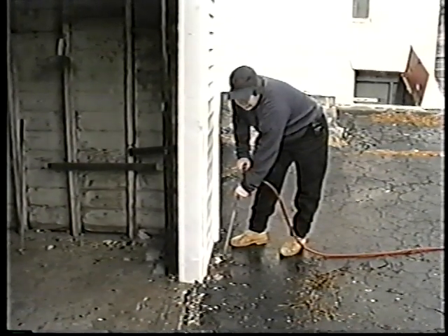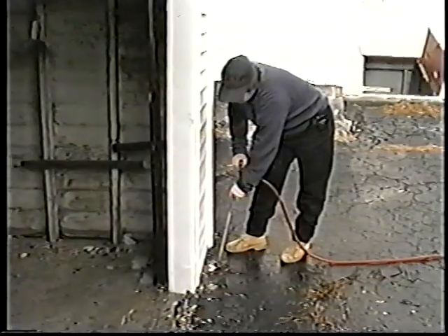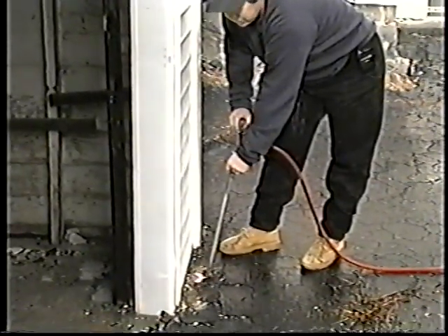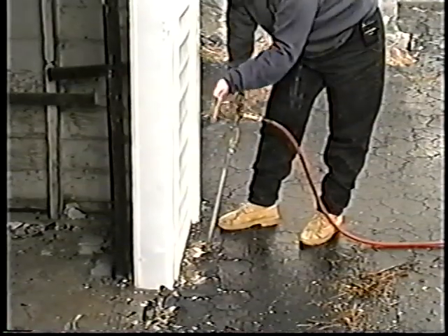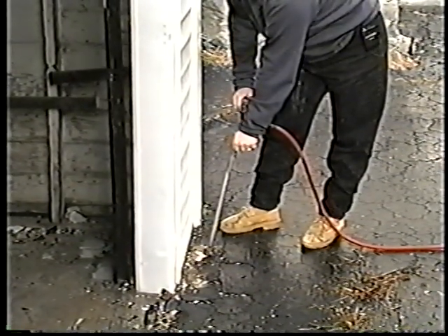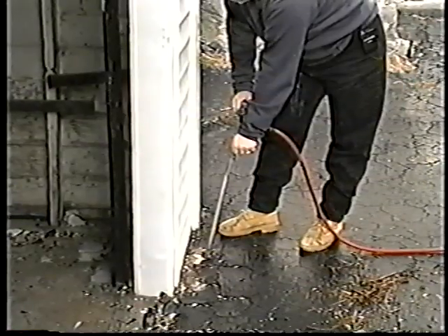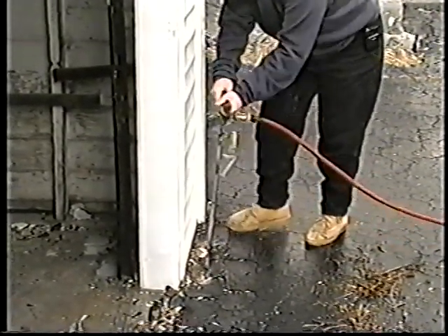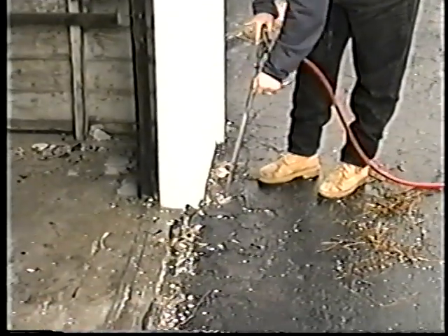If this was just dirt out here, what we would have done is actually dug a bit of a trench with a little trenching tool like a pickaxe. It's light, and then we just fill all the soil in. It's easier than actually drilling in some cases, and we actually treat all the soil. And then once we finish treating all these holes, we plug them up with concrete.